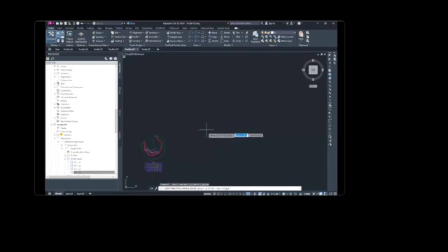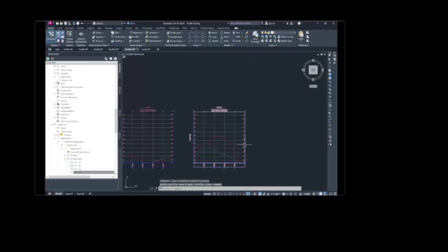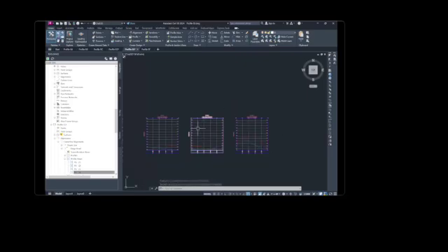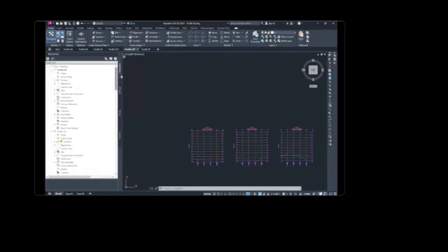Pan and zoom to a clear area in the drawing window. Click to create the profile views, and then we can see the 3 profile views. Good. There we go. Alignment, centerline alignment, then Oak Road and profile views collection. Notice that a separate profile view was created for each 500 segment.